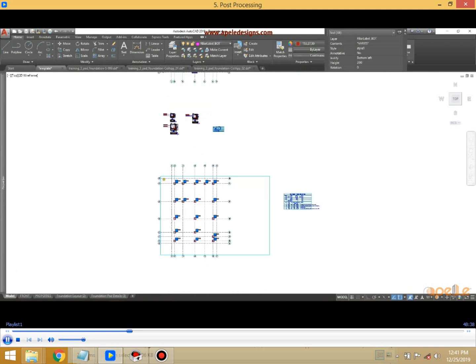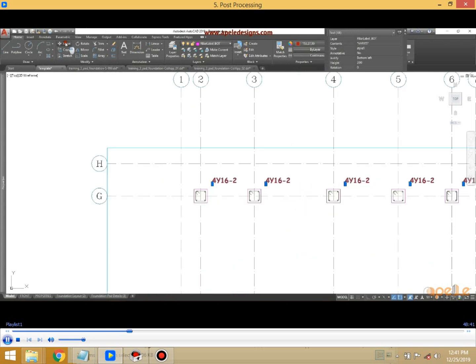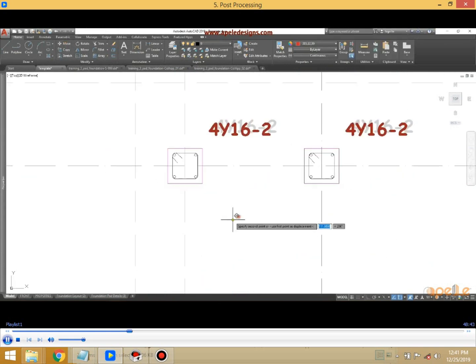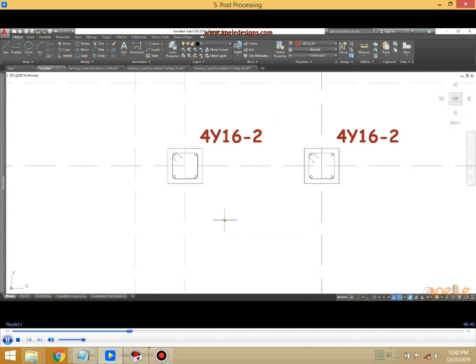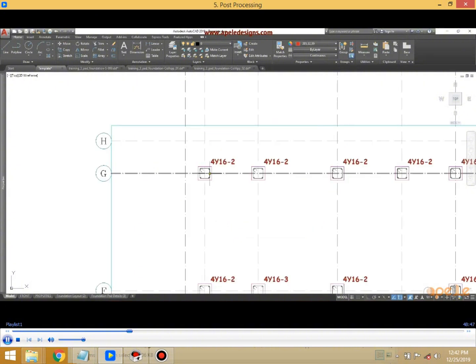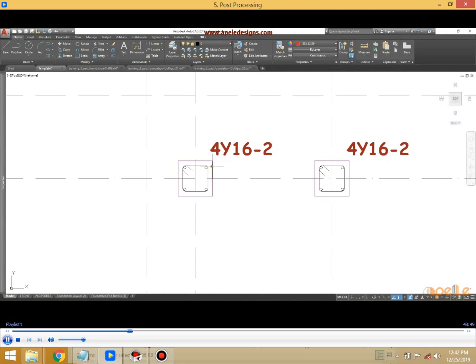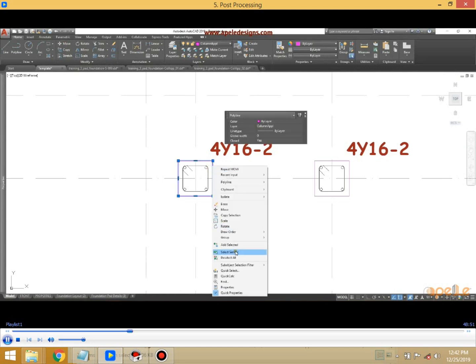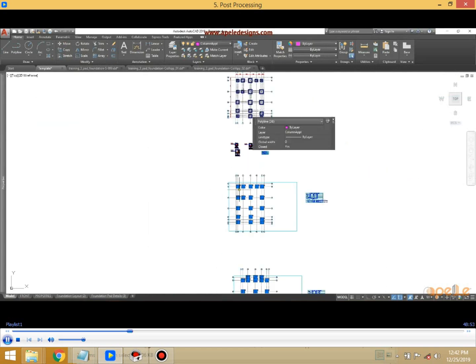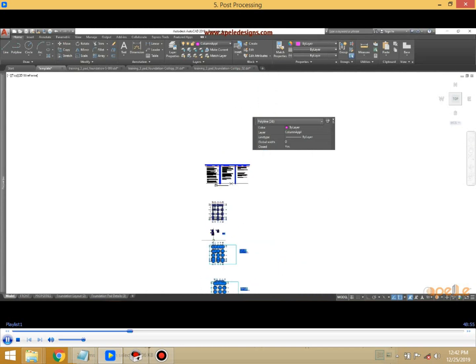And I'm gonna move it a little bit. Just move it slightly towards the column. And I'll pick on the column. Right click, select similar. Ensure no other thing is selected. And to play safe, hold down Shift, remove. Hold down Shift, you secure.